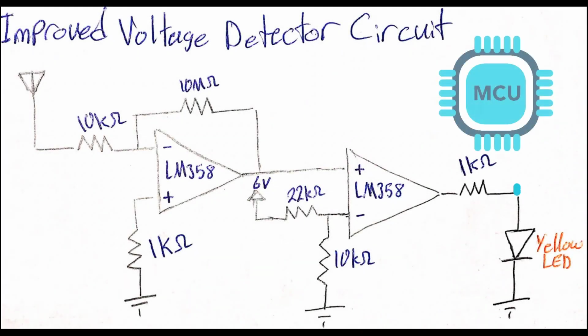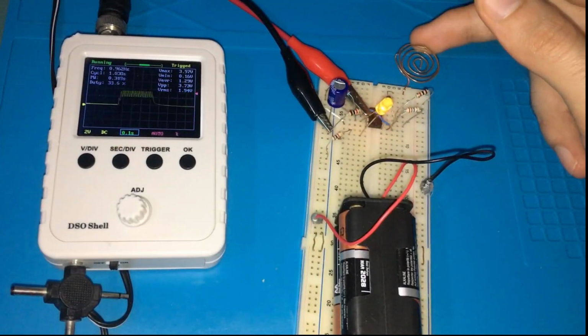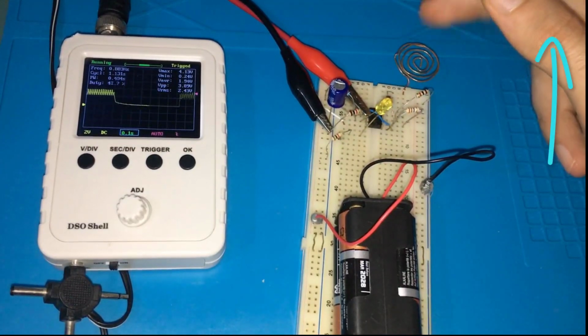If you want to connect the comparator output to a GPIO pin of a microcontroller, it's possible to connect a low-pass filter to the comparator output. And here's how the signal looks like after connecting a low-pass filter. If you want to learn more about high-pass filter and low-pass filter design, you can watch the RC filter design episode from the card shown above.